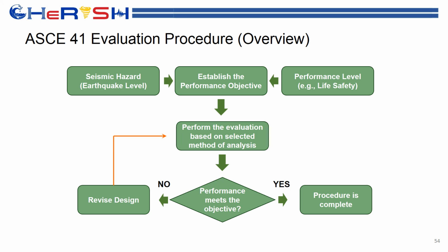For example, in Tier 3, we need to do nonlinear analysis, and there are several things that you should do before you can complete that type of analysis. So this really just shows you the overview of doing a detailed assessment, in particular in doing Tier 2 and Tier 3 analysis after you obtain the RVS result and after doing the semi-destructive and non-destructive tests that were presented to you today.